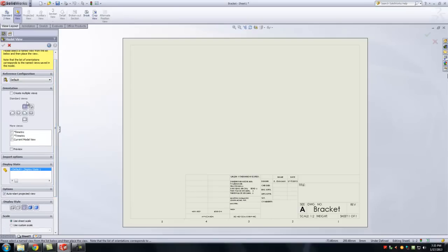And here's the deal. Now, do you remember this? Remember the glass box that we talked about? Doesn't this look like the glass box that we talked about before? Okay. So remember, the front is the main one, so I'm going to click on front. Okay. Now remember, I can make the front directly hidden. So I can come here to display style, and I can automatically select the second option to make hidden lines visible. Okay, so front, which is the center one, and hidden lines visible under display style, which is the second one.